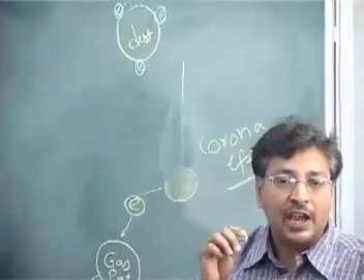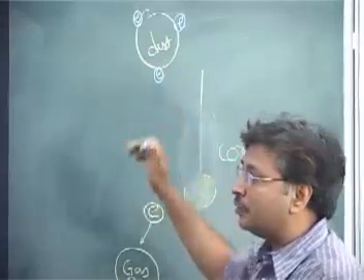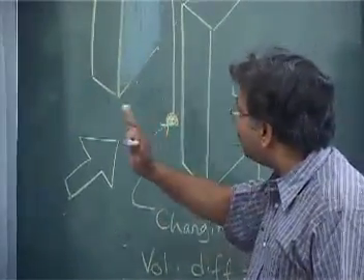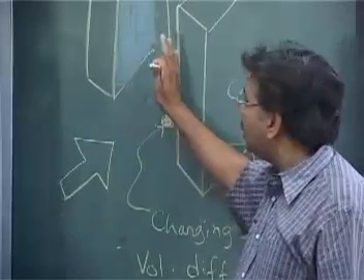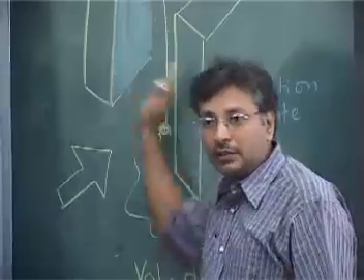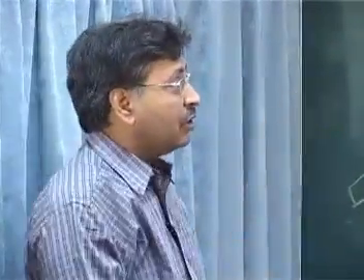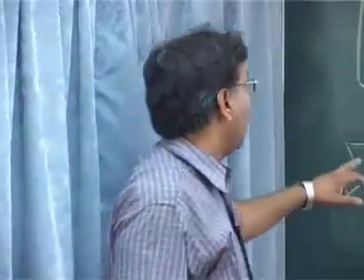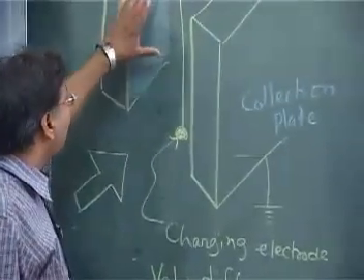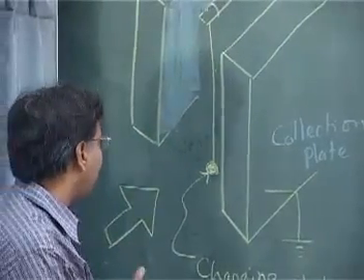Nothing from the inside, nothing at the atomic level, they are just sitting onto the particle. As a result, these particles, which were otherwise going straight, tend to have a migration velocity towards the plate. So this is what happens. You see the corona effect very close to this, and then these particles form a little cake onto the plate.